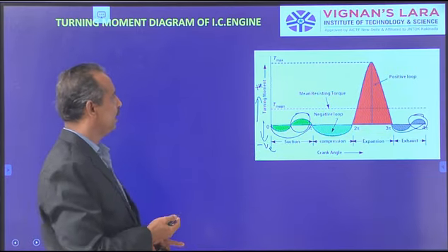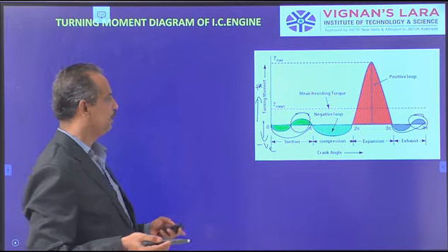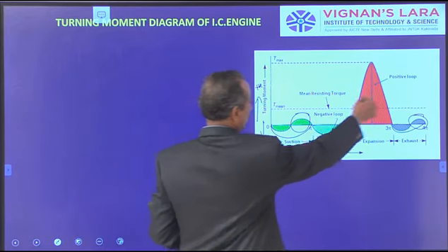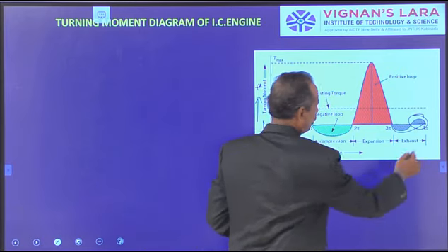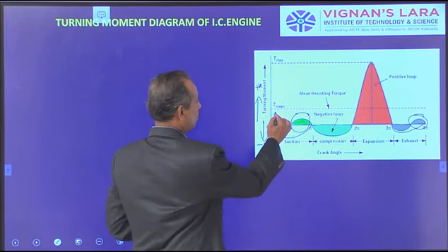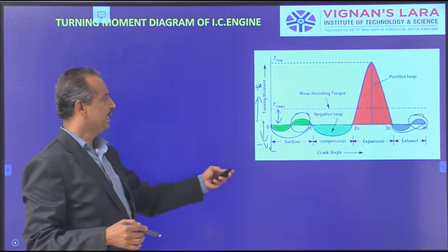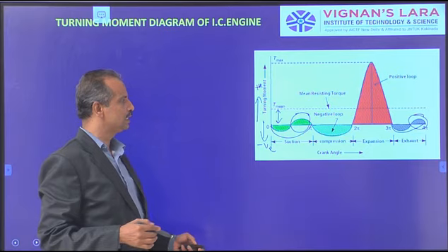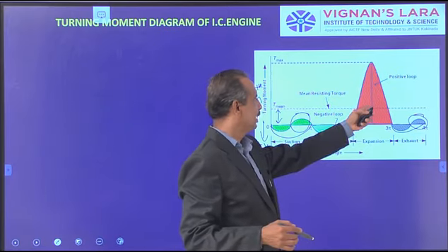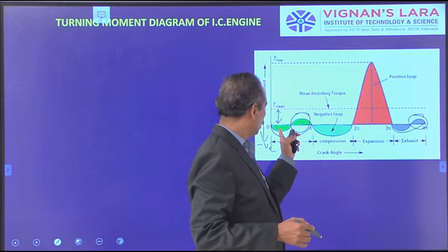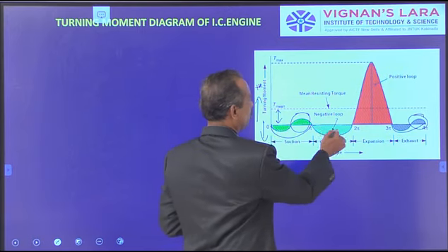In a similar way, like what we discussed in the previous case, here also we can define a mean resisting torque. That means the total area divided by 4 pi gives an amount called T mean. In the previous case, I showed the areas of 2 triangles which I divided by 2 pi, whereas here there are 3 positive areas and 3 negative areas.